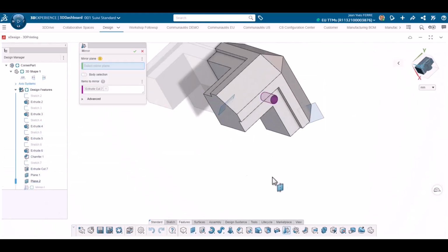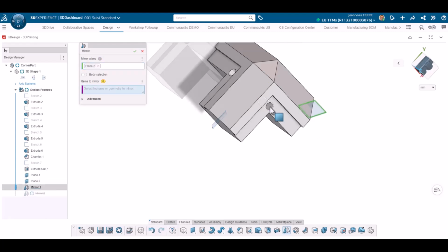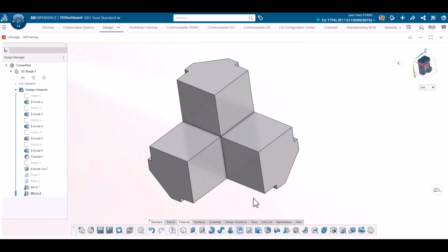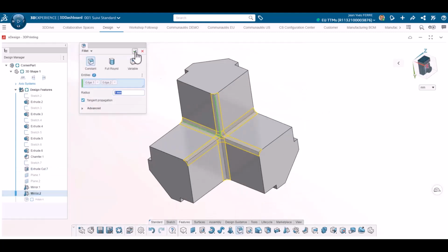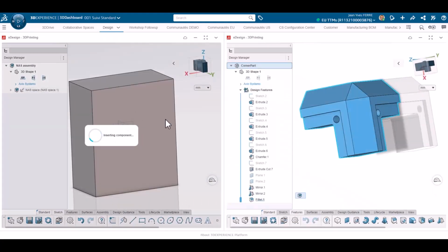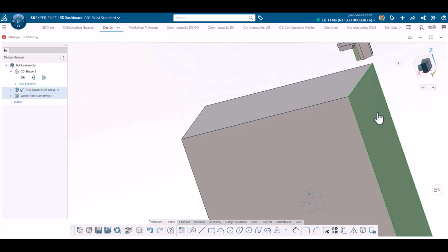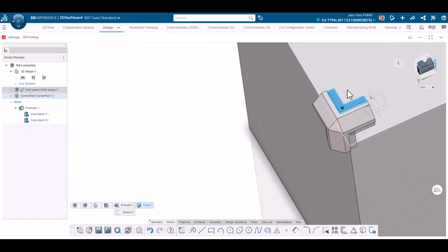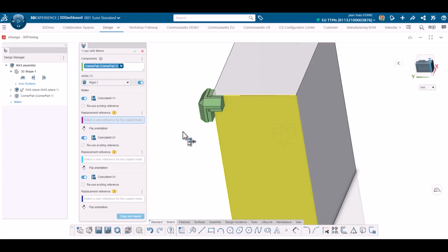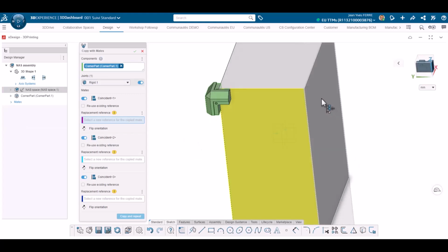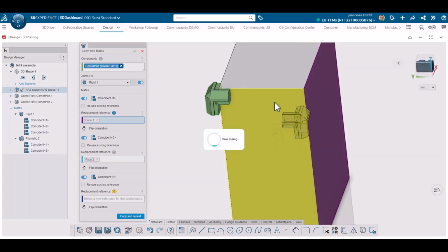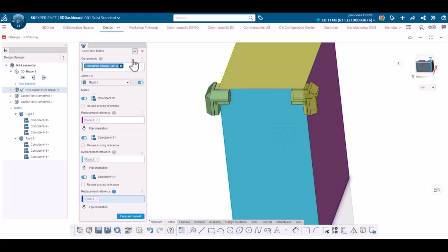I finish outside shape with a fillet and place my part on the box I told you about in the last episode. This box represents the space needed for my computer components with simple parameters like a rectangle and an extrusion. I just need to add simple mates to this box, and I know there will be no interference with my components. To speed up positioning of other corners, I leverage copy with mates, and my 8 corners are in place.